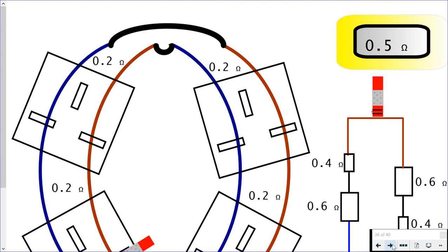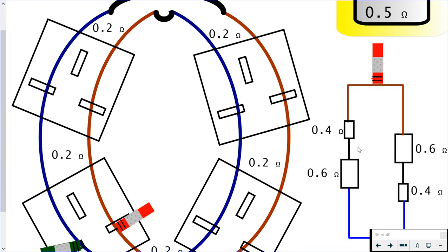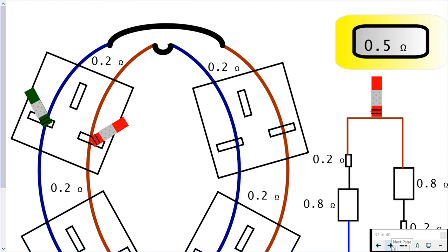And as we run round the circuit, you will see that the resistance values do not change either side. Okay, so we should get consistently the same value as we run round the ring. All right, okay. And you would repeat that for the little r1 plus little r2, so the r1 plus r2 test that you would do between your line and your earth. Okay, and you're expecting to get the same